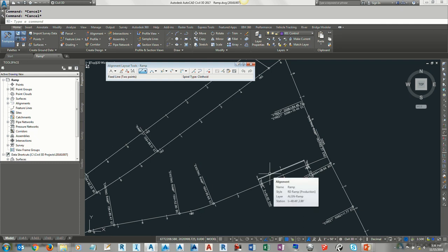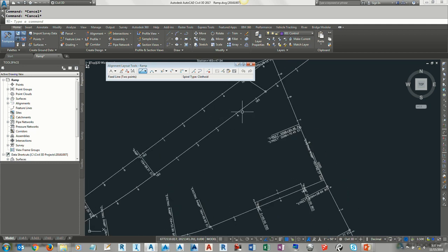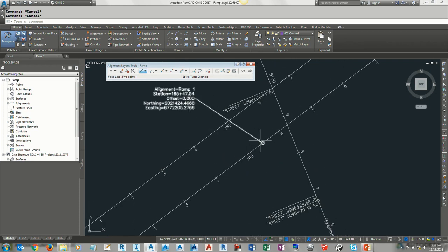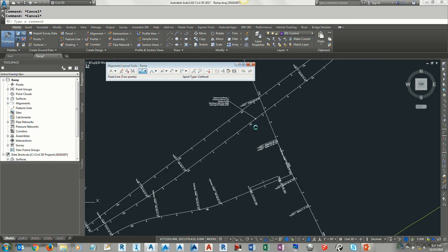So this is my first, and the reason I started with a small sample is I can extend this one to meet the other street, and I don't know where the PI point on this side is. So I just have a small sample. This is the last part that Civil 3D would actually do for me. When I fit the curve in there, it would extend the tangent and find the start of the curve for me. So I leave it at some small default number here. The criteria from the Highway Design Manual of Caltrans is, once you know the point, this is the point that I have marked, the point of tangency with the alignment center should end.